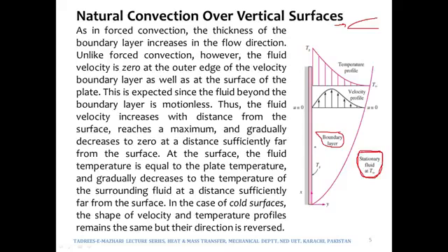If you take a look at this velocity profile, when we move away from the plate, the velocity increases, and there comes a time where the boundary layer ends, after which the velocity again becomes u infinity. But since over here u infinity is zero, the fluid is in fact stationary. You can see over here the velocity will increase as we move away from the surface, because its effects will get lessened, will get decreased.